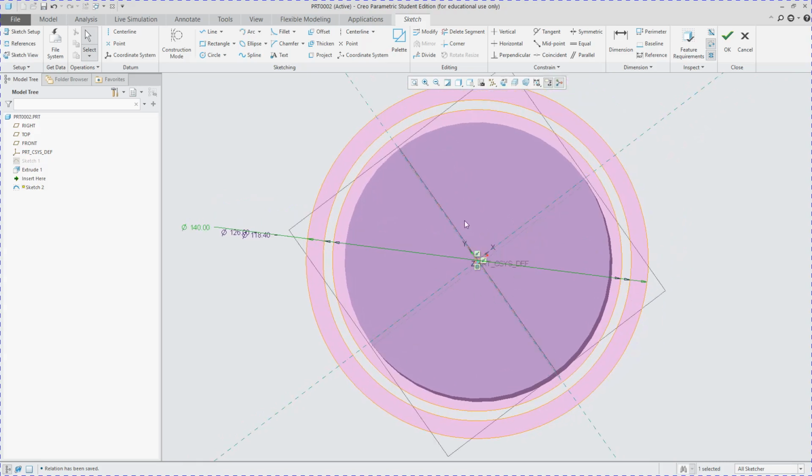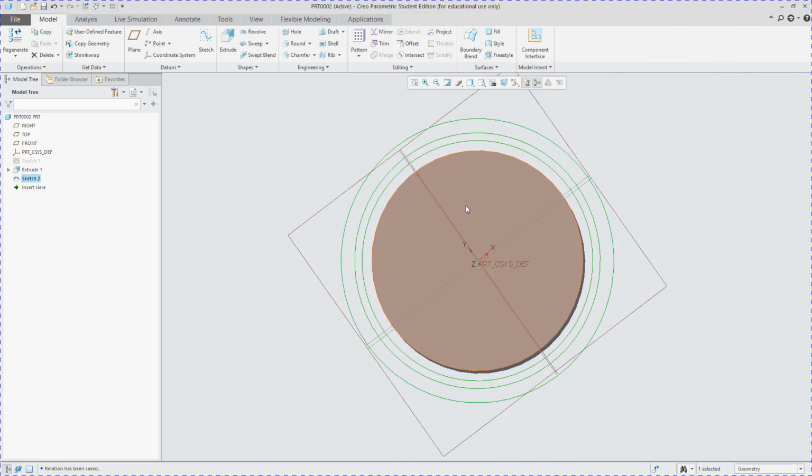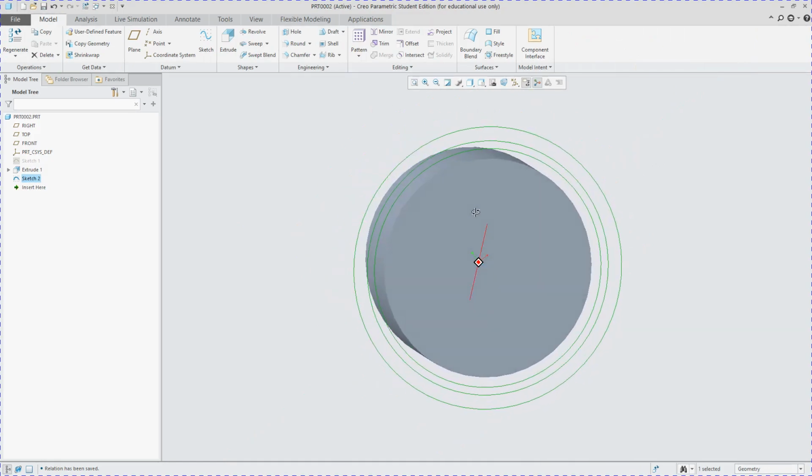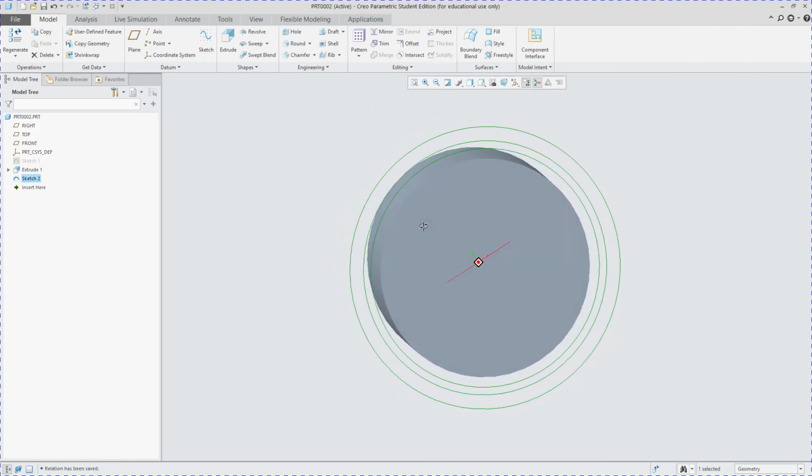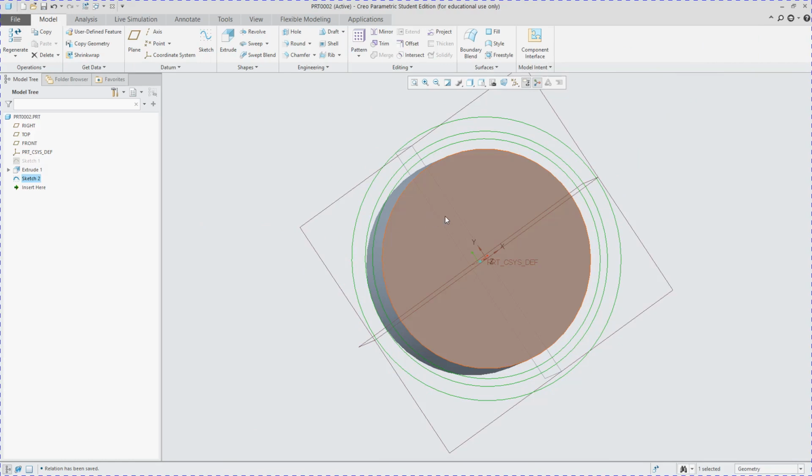So, now you can see that we've got all of our circles, and these circles are what we're going to use to now draw the tooth. So the next important section is to draw the involute. Because the tooth of a spur gear is, I think the standard is based off of the involute shape generally. That's what we're going to go with.